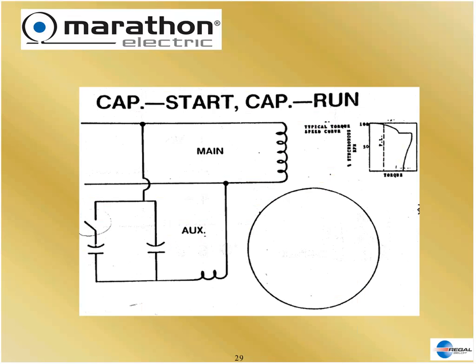Now our auxiliary winding is not going along for a ride, it is helping us in the run condition produce better efficiency, lower amps, and more horsepower really. And that's why pump people really enjoy this motor, because they can get more horsepower out of the same size motor on their pump than they could with the previous one.